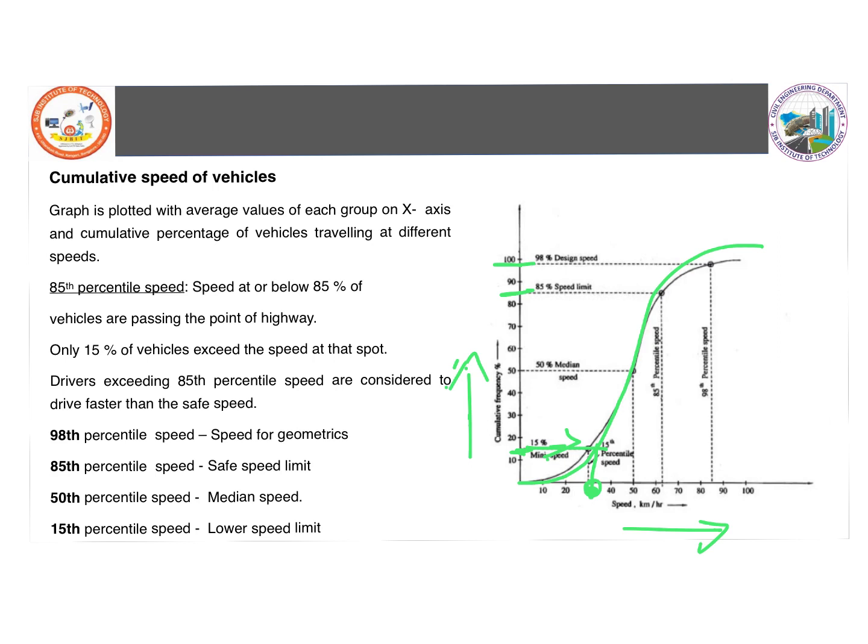What does the 15 percentile speed indicate? For example, say I got the speed here as 30 kmph. Out of all the vehicles, 15 percent of vehicles are traveling at a speed below 30 kmph. Now take the 85 percentage: plot a line at 85 percentage and drop it down.